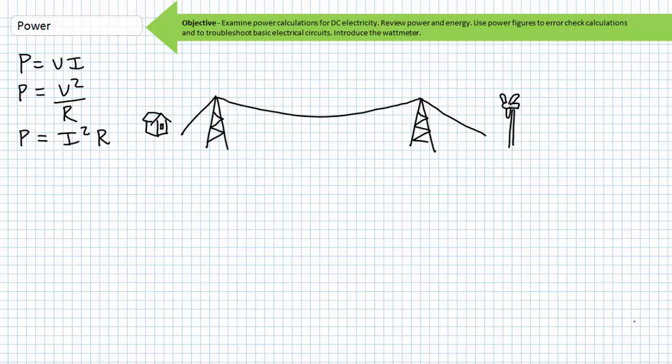power is transmitted using high voltage rather than high current. I know transmission is typically AC and not DC, but let's pretend they're equivalent right now. Let's say you're trying to transmit 2.3 megawatts of power from a wind turbine out in the sticks to a city located in the shoe-wearing regions of the country, and the super long transmission line is modeled as a resistor with 7 ohms of resistance.